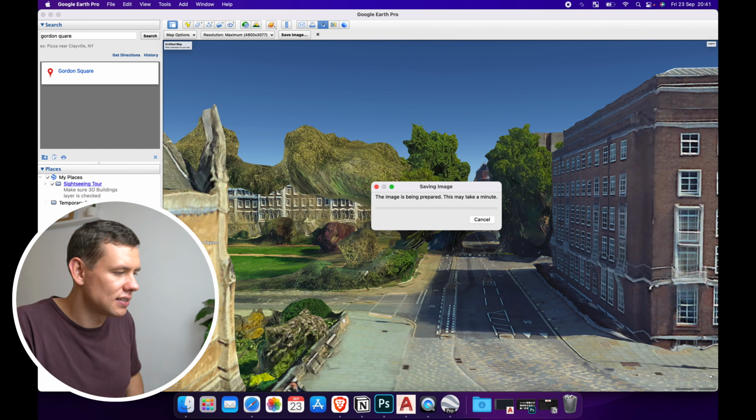The typical rule of thumb that I usually use when I produce context elevations is that I try to keep at least one width of the building next to it. So if the building is, I don't know, 20 meters, then I'll draw the adjacent context 20 meters away from that. So I'll save this last slide as well.